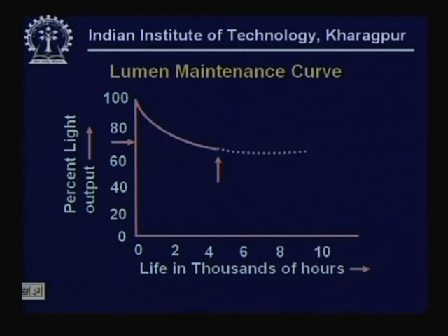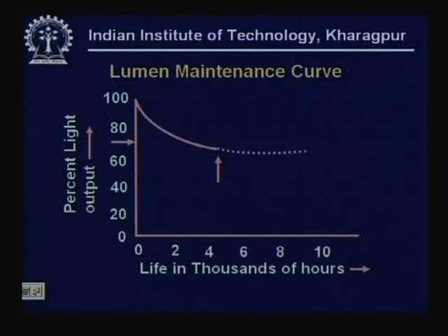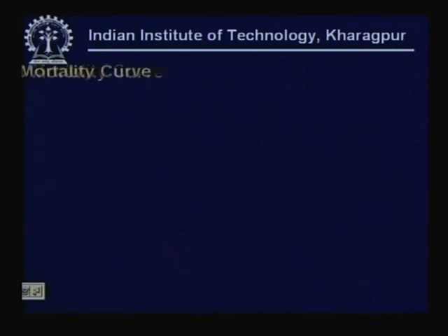This is a very important issue. That means if I take a lamp which has say 1000 lumens in a virgin state, for a very long period, assuming other factors like the phosphor coating remain and filaments are stable and intact, the lumens or the light flux will be maintained reasonably around 700 lumens. That is the thing which one can interpret out of this curve.